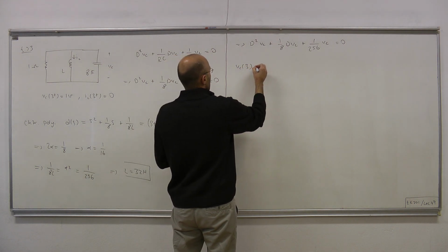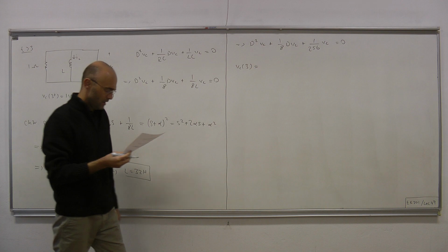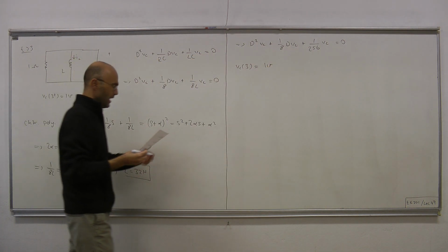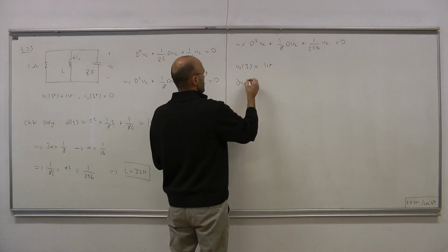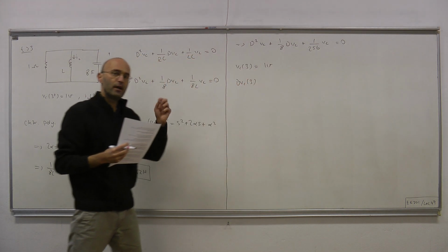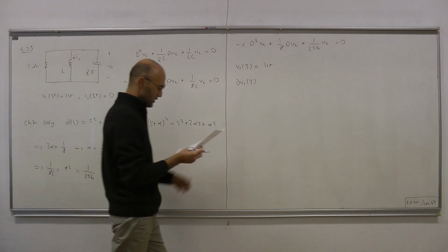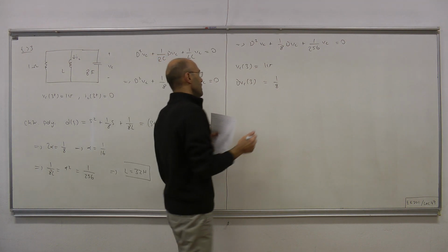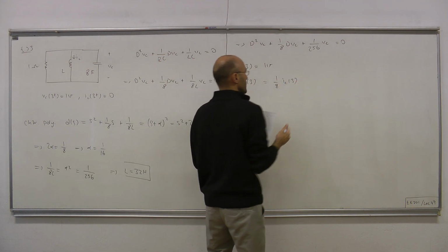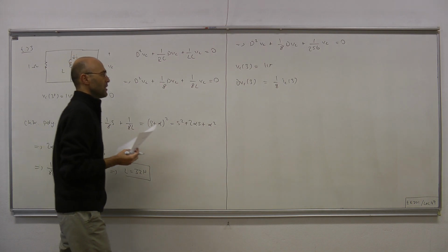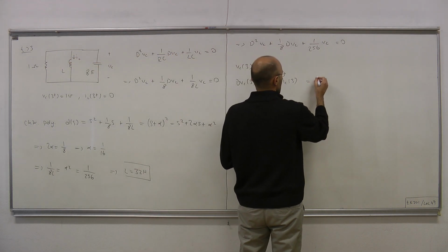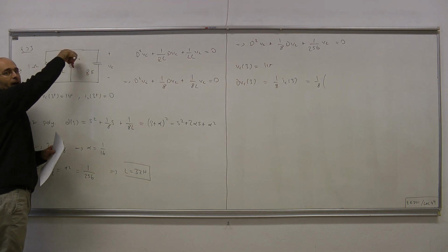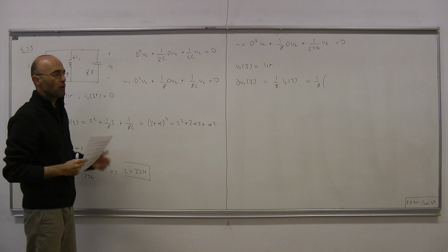Vc initial condition, Vc(3) equals 1 volt. And dVc(3), the initial condition for the rate of change of the capacitor voltage, is what? So that equals 1 over C times IC, using the terminal equation of the capacitor. IR plus IL plus IC equals 0 by KCL.